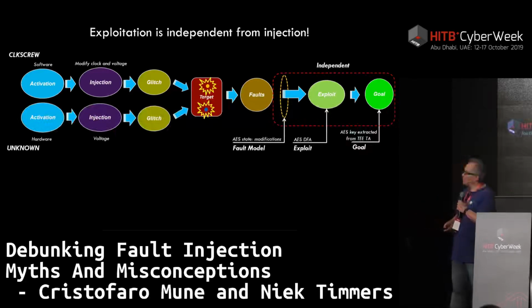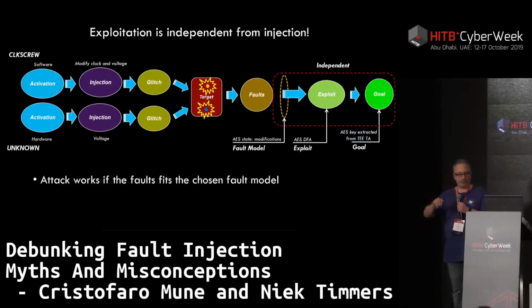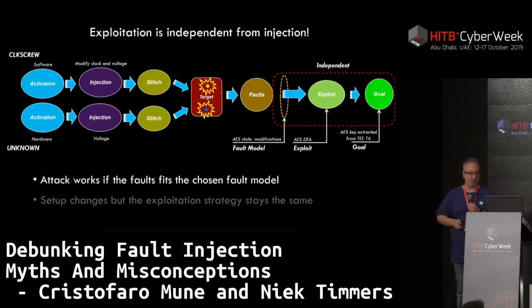So this means that if you switch from one attack, one injection technique to another, you may be able to completely reuse what happens for the fault leveraging. So the attack will work if the faults fall within your chosen fault model, because the exploitation has been designed to use those faults. And that is the important part.